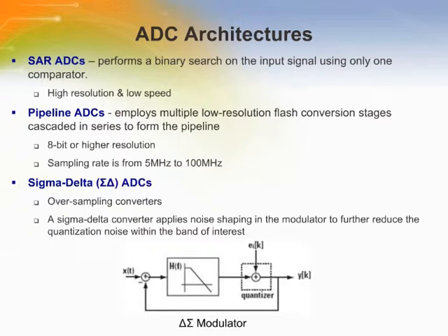The basic principle of operation for the sigma delta modulator is to enclose a simple quantizer in a feedback loop to shape the quantization noise such that most of the noise is shifted out of the band of interest, where it can later be suppressed by filtering.